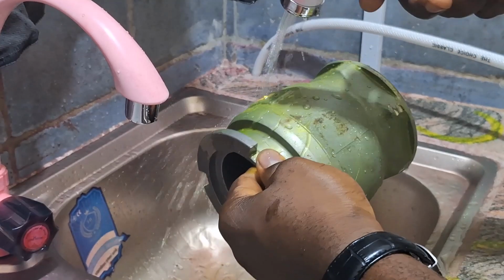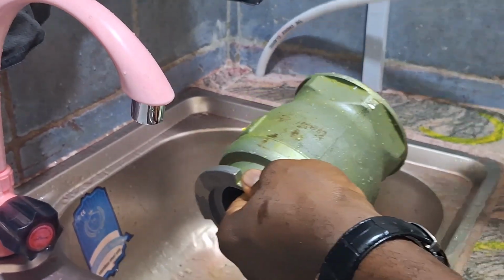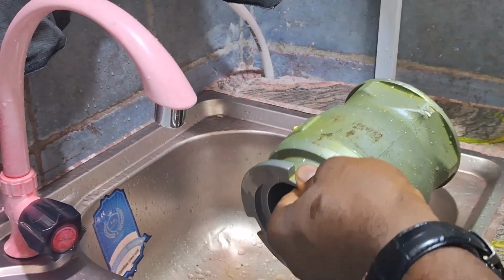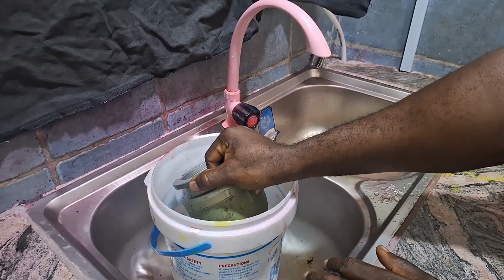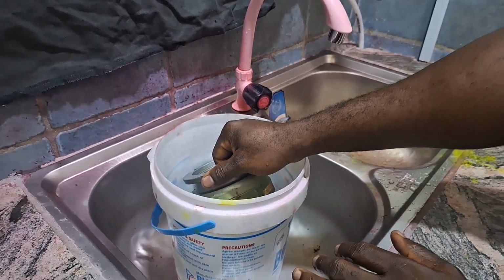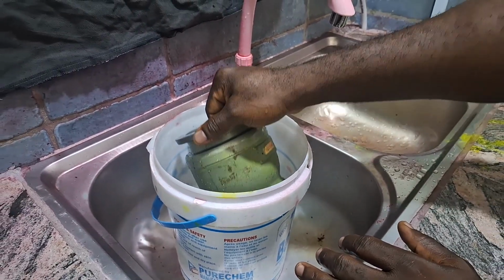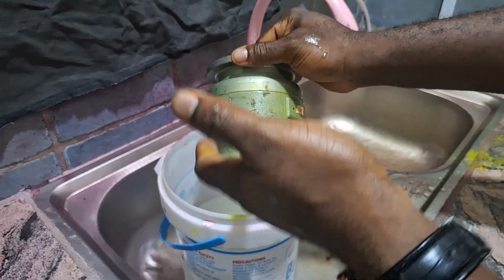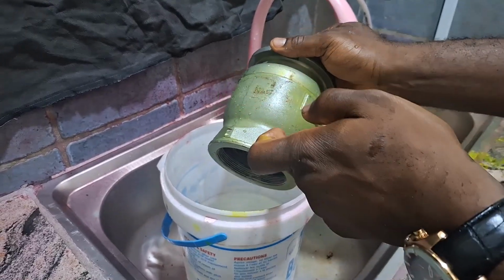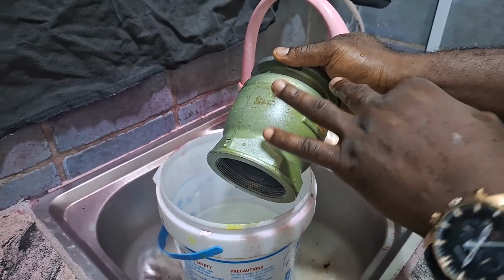Take note, this is for hydrophilic. For lipophilic, you don't do this. So after doing your pre-rinsing for your hydrophilic, before you now put it into your emulsifier, maximum 30 seconds, because if you leave it more than that time, it's going to remove both the ones that have dissolved into your crack and indications, and you are not going to see anything by the time you develop.